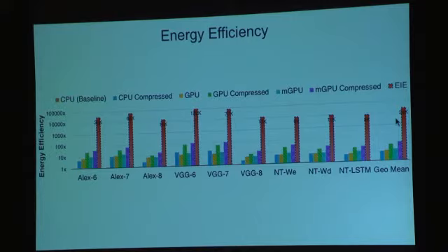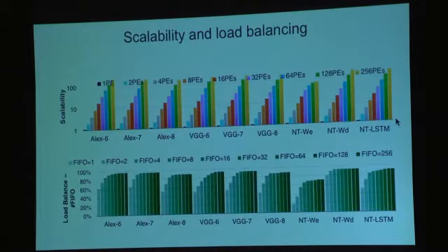And the reason it's only 24,000 is that this is implemented in a 45 nanometer process. It's about 6 generations back. It scales well. This basically shows as you go from one processing element to 256 processing elements, how the performance scales. Some of the networks start topping out at around 64. Most of them scale pretty linearly up to 256. And I should say this is strong scaling.